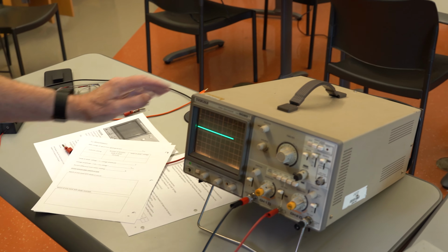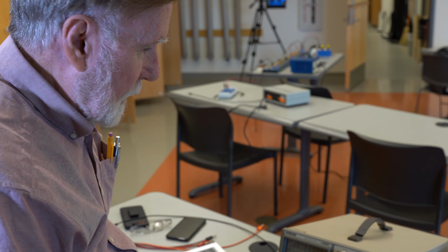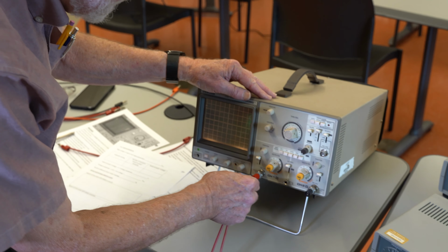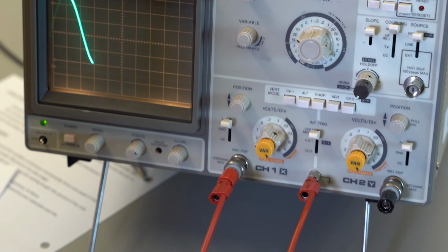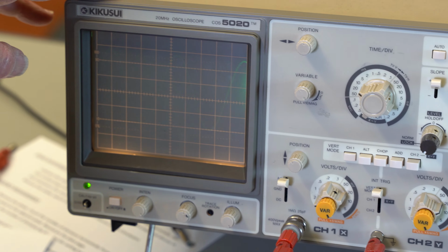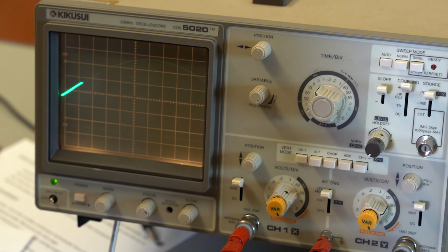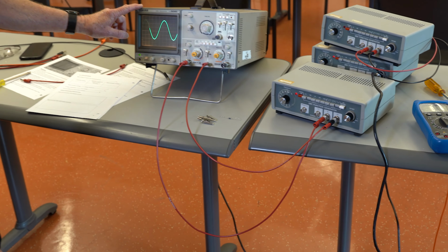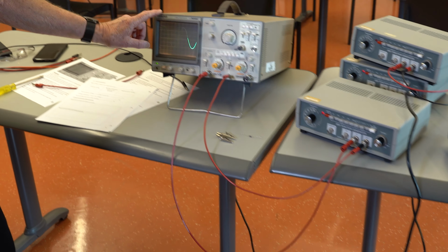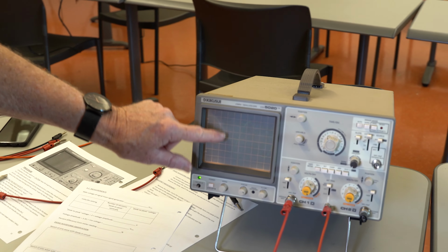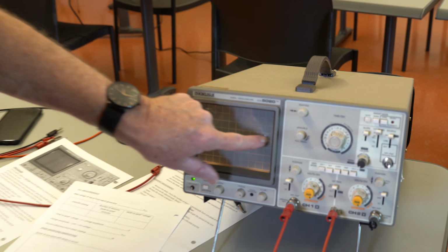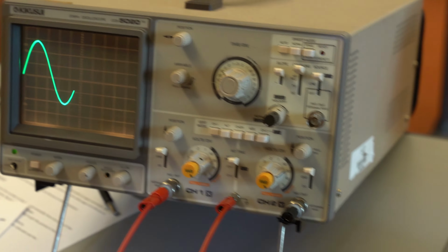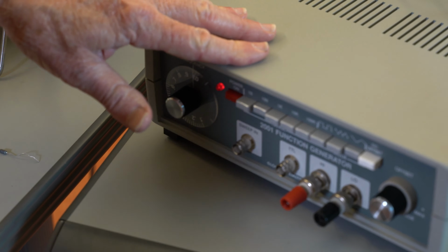Let's see if we can measure it on our oscilloscope. We've got a frequency generator here that generates an AC signal, so now we're going to use the oscilloscope to show the AC waveform. That's one of the things oscilloscopes are used for, to check out the waveform of an electronic component. We remember, vertically we're measuring voltage, and on the horizontal axis we're measuring time, basically how fast it's going across the screen. So let's check the voltage output of this AC generator.